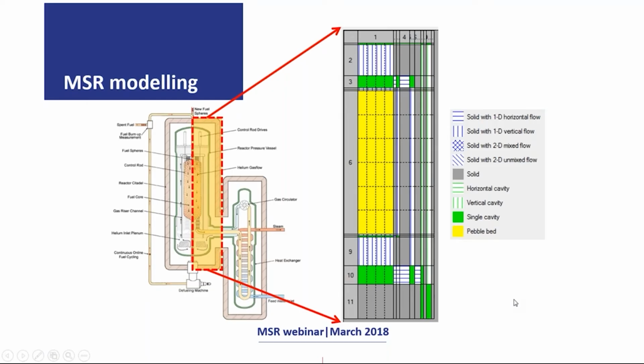So in Flownex, the first step will be to set up this geometry chart. We call this the geometry chart, and we build this with these blocks. So you can see there's various columns and various rows, and each of these I can name according to this region. Let's say a pebble bed. There's also a general field zone that I'll introduce you to just now, and then single cavities. So all these regions, I can use them as building blocks in order to create my geometry. Remember again, it will be half the geometry in one plane that will be revolved 360 degrees.